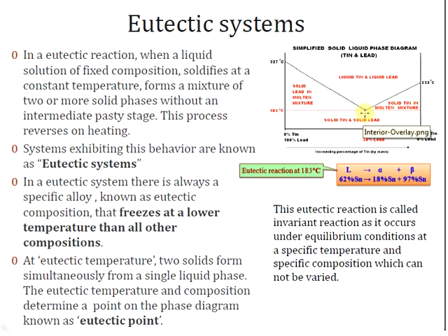But this is happening at a low melting point when compared with these two. This alloy melts at a point lower than these two points. Such a point is called the eutectic point, such reactions are called eutectic reactions, and a system exhibiting this kind of behavior is known as a eutectic system. In this tin-lead example, the liquid composition at this point has a weight percentage of 62 percent tin, and it transforms into alpha.